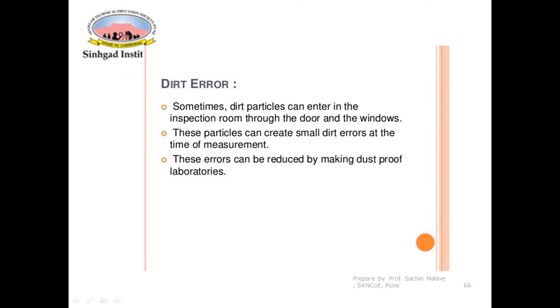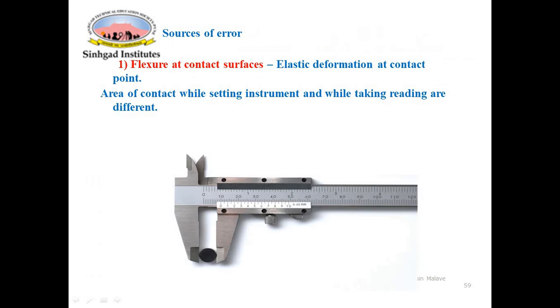In case of the analog, I will show you one more sketch of this vernier caliper. Okay, you can see, this is the analog vernier. Here you are not going to get any kind of display. In this vernier caliper, the scale on this fixed beam is called the main scale. On the main scale you can see some numbers shown, say 0, 10, 20 and up to 120. And there is one more scale here which is called a sliding scale, also referred to as a vernier scale.